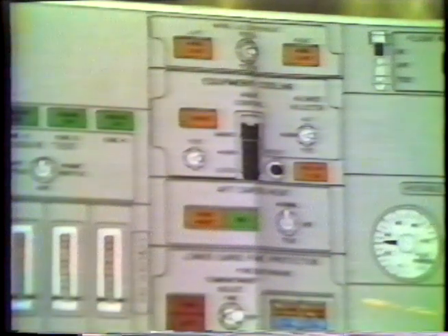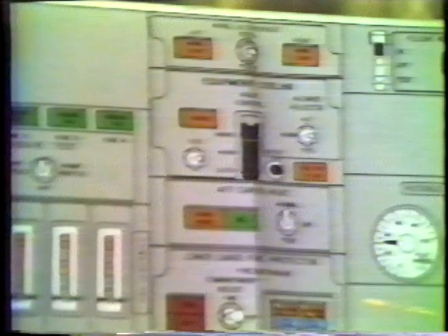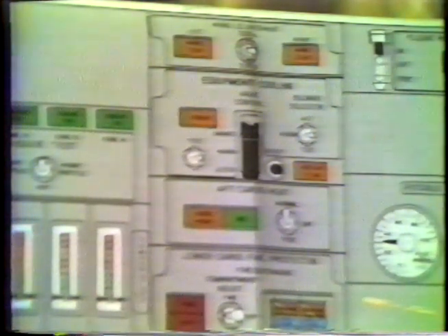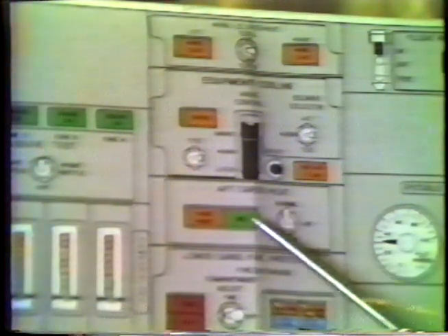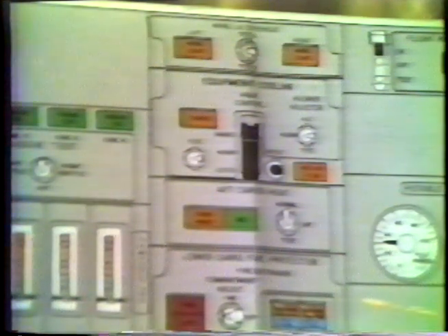When putting the switch to normal, the temperature control will cycle the valve to the open position when it starts cooling off back in the aft cargo. Generally what happens in climb, the light might come on and go out and then come on for the rest of the flight and then go out on descent. Normally in cruise the light is on all the time. If the valve should fail in the normal position, the overheat valve can take over in a cycling function. If the overheat valve does not cycle, then the cargo heat should be turned off.